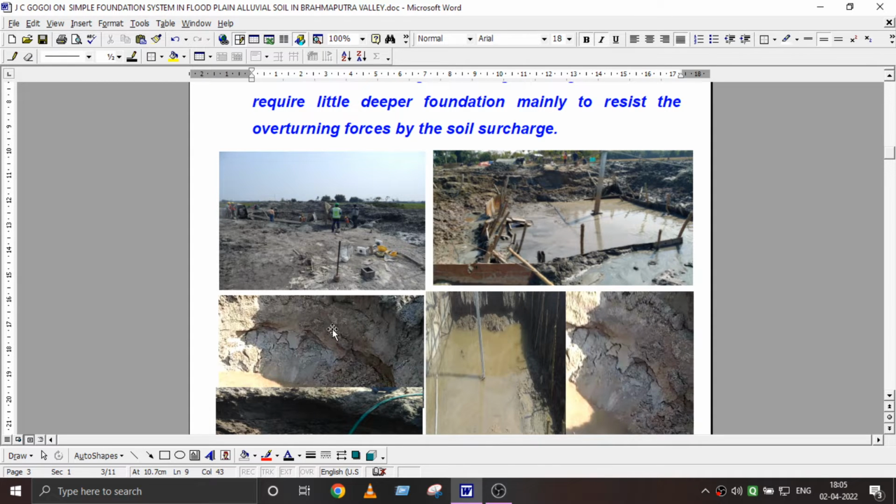Besides that, when the soil has zero shearing resistance at the bottom, the weight of the upper soil is not resisted by the soil strength at the base. So automatically there will be slides or soil slips, which we can normally call instability of the cut slope.